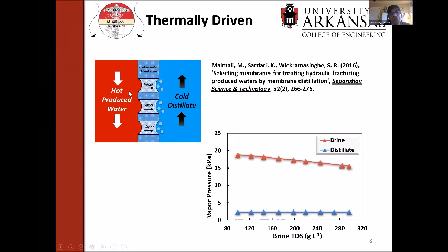And since the membrane is hydrophobic, only water vapor should transport through the membrane pores. The driving force for separation is the vapor pressure difference between the hot feed and the cold distillate. And so one doesn't need to boil the whole feed like conventional distillation. As long as there's a vapor pressure difference, this process will continue.